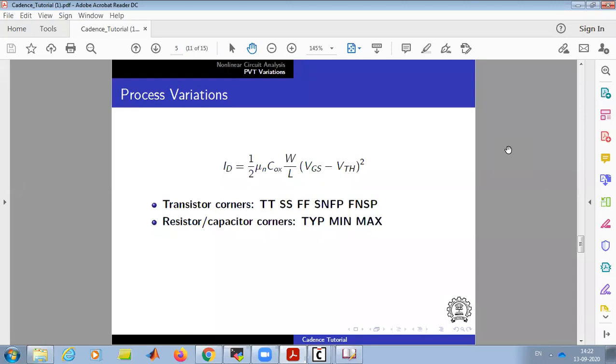So what I want to say is, if you make a transistor 1,000 times or 1 lakh times, every time it will have a lower limit and a higher limit, based on the annealing process and how many dopants get activated. In this terminology, we call those transistors at the lower limit of mobility slow.